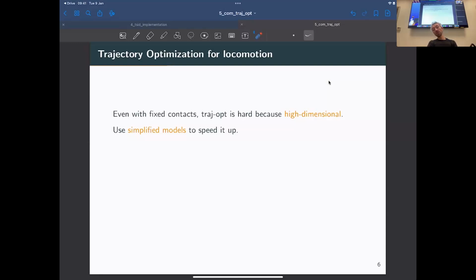And if you're able to do it that fast, actually, we could also do it then in an MPC fashion. So re-executing the trajectory optimization every few milliseconds to update the reference trajectory, not to use a fixed one, which will make the system much more robust to perturbations.